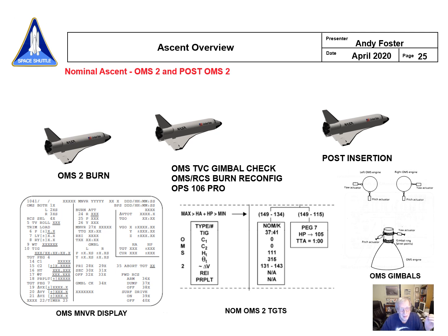Burn attitude and all that for the OMS burn here, here, here, and then they track it over here. This shows them how much velocity they have to go in the burn, time to go, and all that kind of stuff. And HA-HP would show right here. This is your target HA and HP, and then current HA and HP. And so we'd use this OMS maneuver display, do the OMS 2 burn.